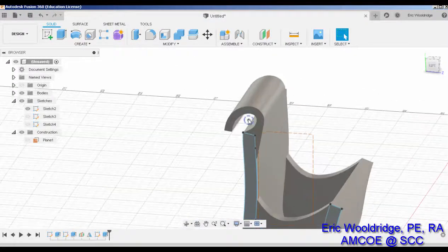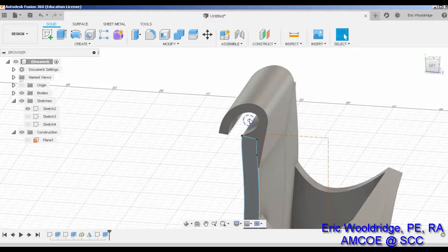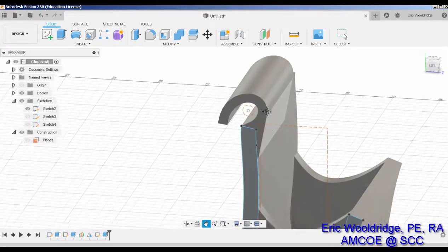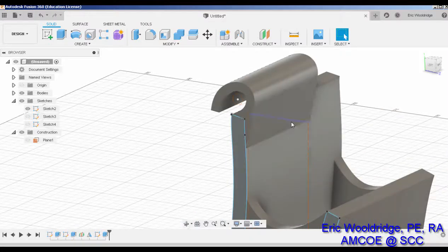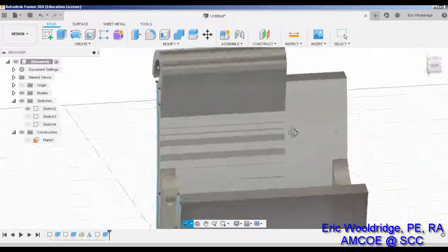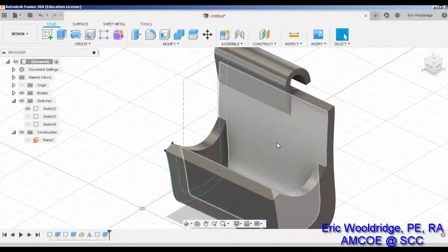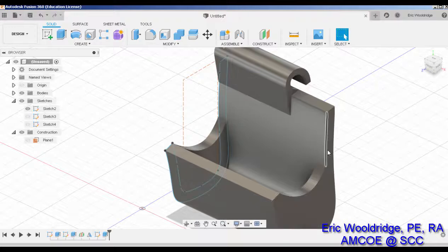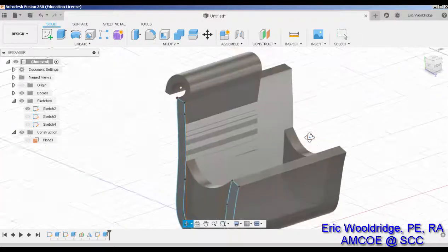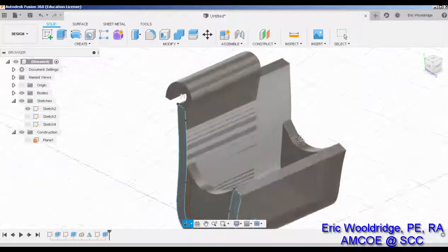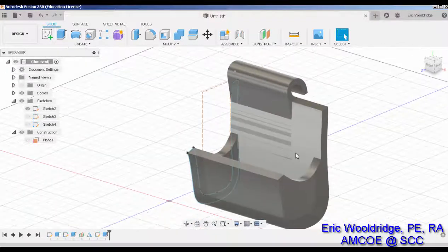So assuming that I got the wire size right of the shower frame system, or the shower caddy, that will work. And I always have control to come back and reshape this after we print it to actually modify it. Now, if I were designing it to go straight to printing right now, there's a lot of areas I could optimize. I don't need this much solid structure. I would thin out the wall. But where I'm probably going to go is take this into a lattice and then lattice this zone and leave this solid, it will optimize the rest of the body without me having to do a lot of work. Okay, so creation made. Features cool, and overall shape's good to go.